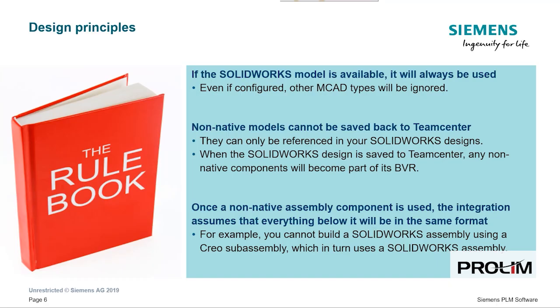Several rules are observed by the Teamcenter SolidWorks integration, when working with non-native design data. First, if a native SolidWorks model is found, it will always be used. Any other MCAD file, even if configured for reuse, will be ignored. Non-native models that are opened or inserted from Teamcenter cannot be saved back to Teamcenter as SolidWorks models. This preserves their identity and avoids duplication of designs under different CAD formats.